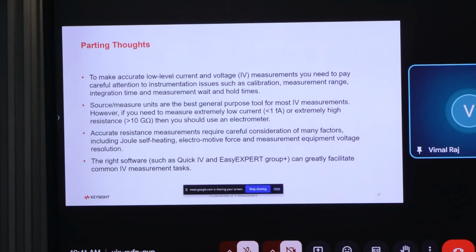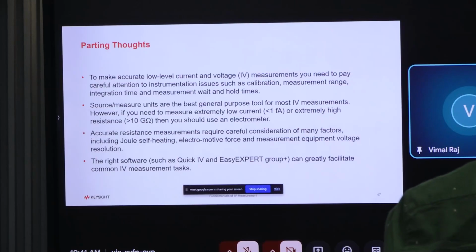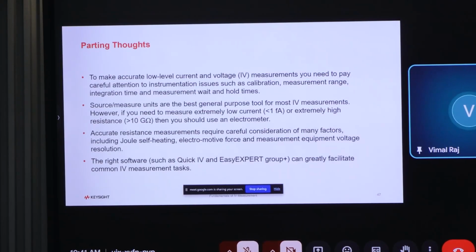the looping of the grounding effect, and you want to do the average measurement, and you can avoid the power line cycling effect, and use which cable can achieve low current using the triax, and what the difference is, and how to select the range, which will be reflected in the measurement, and how to avoid the transient effect in the switching. Okay, these are the things we use. It is not special; it is common for all characteristics in the IV.